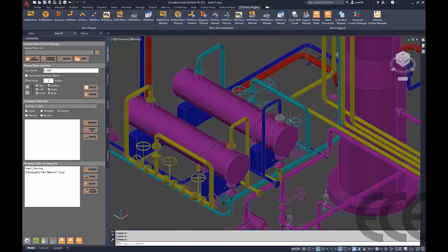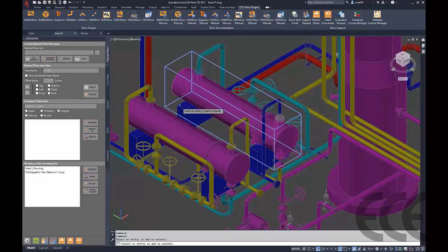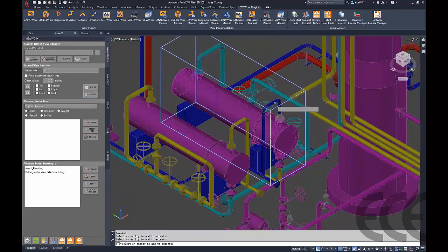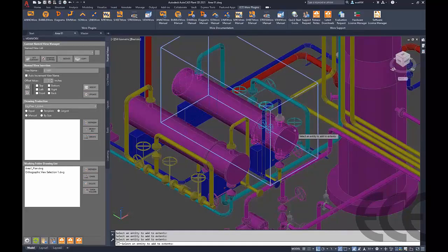On the first one here, we're just going after this control station, so we want to look at the right-hand side of that. These are all based off of the user coordinate system for the world. So you've got your world coordinate system up here. If you ever need to get a quick reference, the ViewCube does a pretty good job of letting you know which view we're working with here. And then we simply insert these by selecting components. As you select each object, we're going to build a box around that object, allowing you to easily encompass everything you need inside of that view.